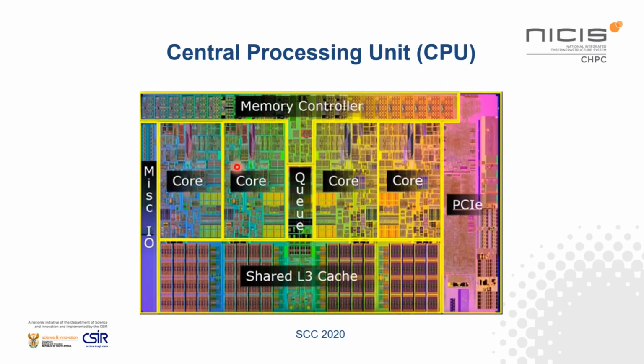As we've seen, a CPU is manufactured through photolithography, where shining light in certain regions of silicon produces certain patterns, which, when combined with other techniques like etching, build the structures that carry out certain functions. That process ends up with something that looks like this, which consists of various regions laid out on the CPU, such as the memory controller, the CPU cores, the CPU level 3 cache, and so on.